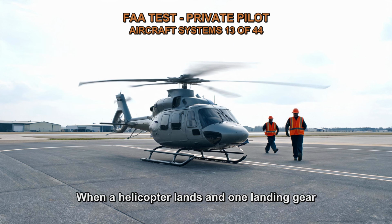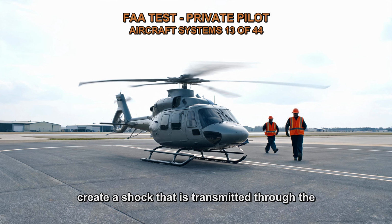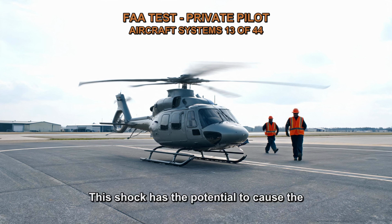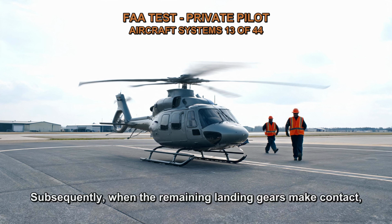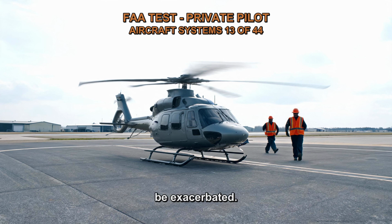When a helicopter lands and one landing gear strikes the surface before the others, it can create a shock that is transmitted through the fuselage to the rotor system. This shock has the potential to cause the rotor blades near the contact point to be forced closer together. Subsequently, when the remaining landing gears make contact, the unbalance caused by the initial shock can be exacerbated.